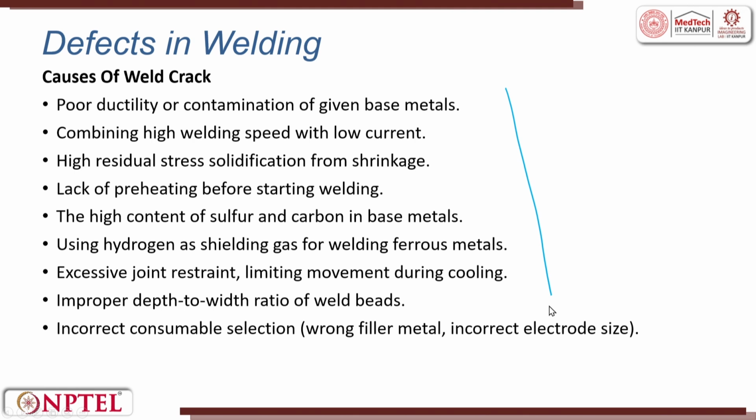Causes for weld cracks: poor ductility, combining higher welding speeds with low current, high residual stress during solidification, lack of preheating, high content of sulfur, using hydrogen as shielding gas, excessive joint restraint, improper depth to height ratio, and incorrect selection of filler or flame. All these things are causes for various types of weld cracks.